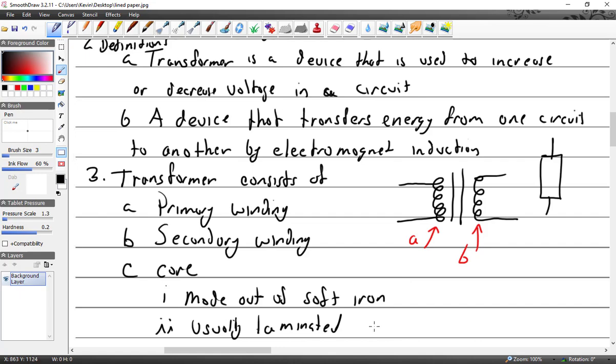All right. This will probably make more sense after we do non-destructive testing. But that's to do with permeability and how magnetism works with iron. You take something like a crankshaft and you magnetize it. It takes more magnetism to line up the domains, but once you do, it's locked in. It stays that way, and it takes more magnetism to get rid of it. But soft iron easily magnetizes, and once you remove the current, it dies off. It doesn't stay magnetized.